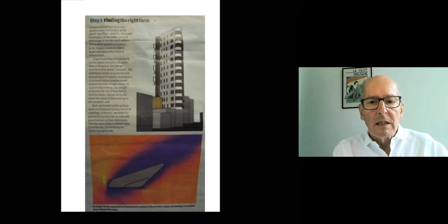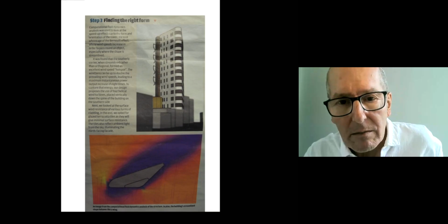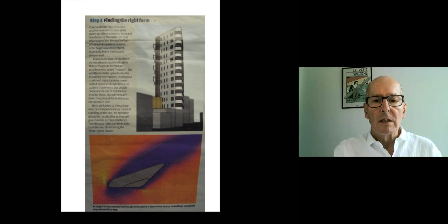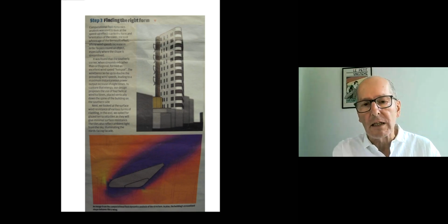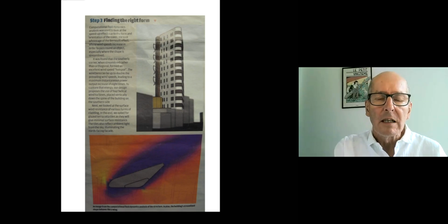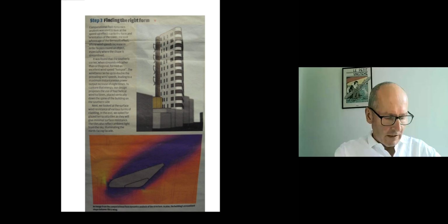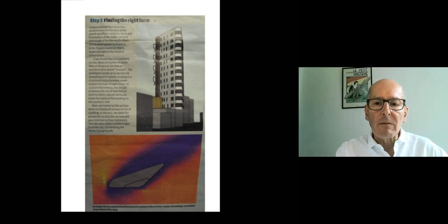We don't often promote putting wind turbines or, if you like, trying to gain energy as part of architecture, either through wind turbines or through photovoltaics or through anything else. I mean, it doesn't seem to be necessarily part of architecture. The important thing, I think, is to be efficient with the passive envelope, with the materials that you're using, with the relationship between insulation and thermal mass, and the amount of glass, and where that glass is in relation to the sun, and so on.